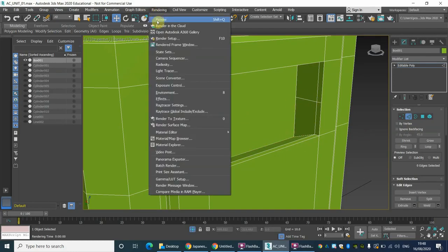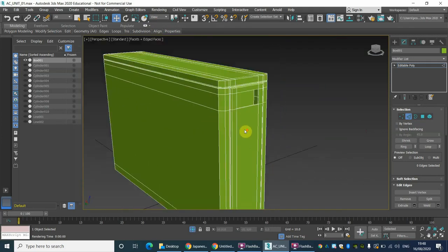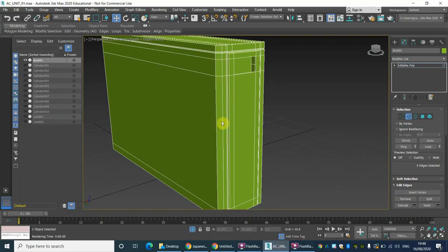Okay, so you're creating a handle with a bit of an edge, as it is here. So if you render that, you'll be able to see you've got some handle going on. Okay, so now we need to work on, so we've done this, we've done that, we've done the little bevel extrusion there, we've got the handle, just need to work on this. So again, now we need to create a couple more swift loops, one here and one there, and then we're going to cut the diagonal line there.